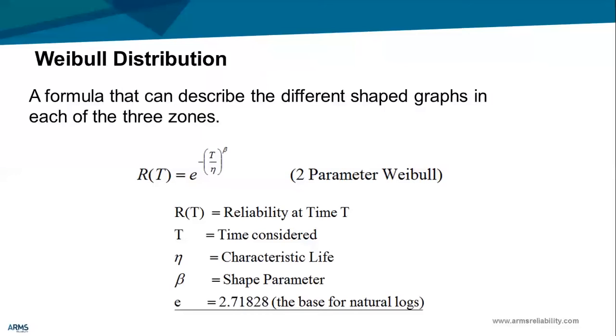To determine how often we need to do maintenance tasks, we need to use a Weibull distribution. And some of you may be familiar with this Weibull distribution. This is the simplified two-parameter Weibull distribution here. Now, this particular equation will allow us to define what the failure behavior is, and also define what the interval is, to allow us to calculate what the reliability is at any point in time, and help us determine how often I need to do my maintenance task.